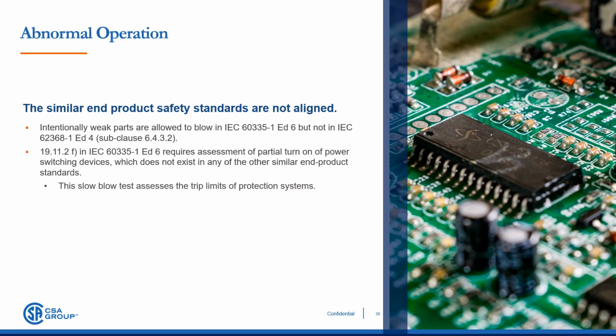Additionally, it is a realistic single fault scenario, as a break of the PCB track or solder connection to the gate pin may leave the pin floating. In such cases, stray electromagnetic fields in the appliance environment may couple into the terminal, causing the component to partially turn on.